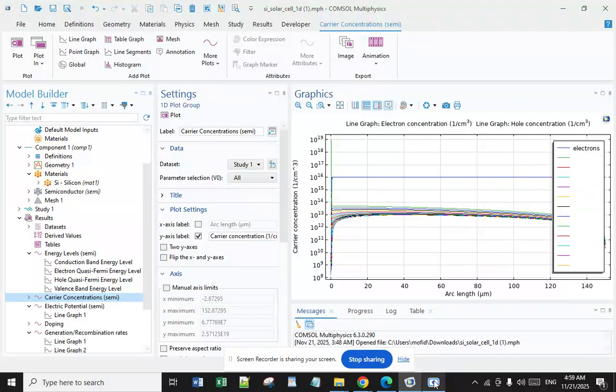The first plot compares donor and acceptor concentrations for up to 10 micrometers beneath the solar cell's front surface, as we see below. While the donor concentration remains the same, the acceptor concentration sharply decreases. To avoid accidental setup errors, it is good practice to check a model's doping profile.